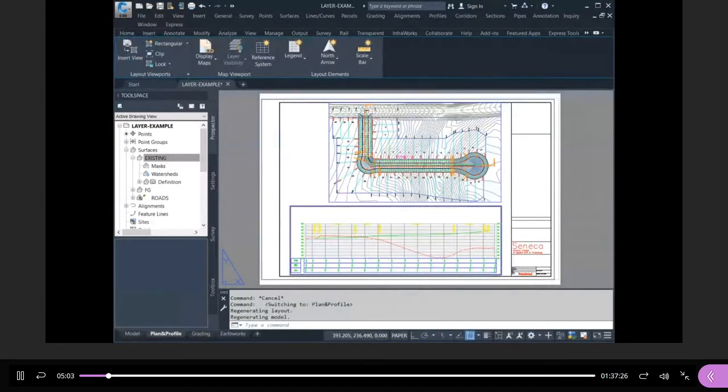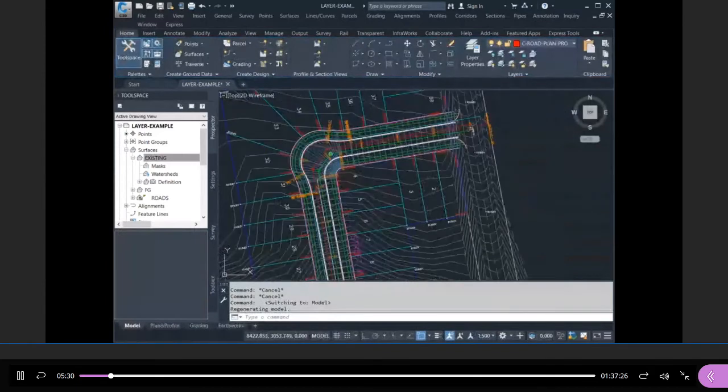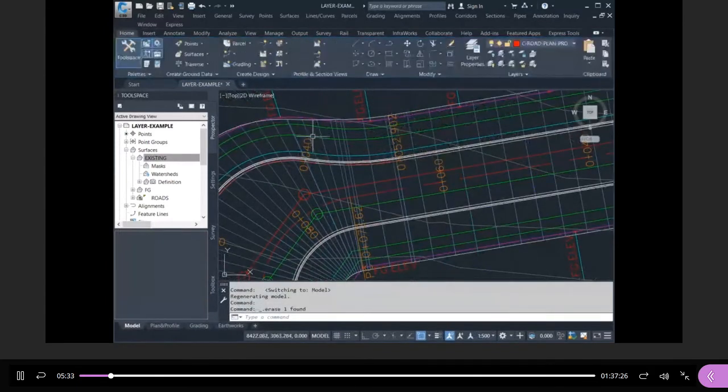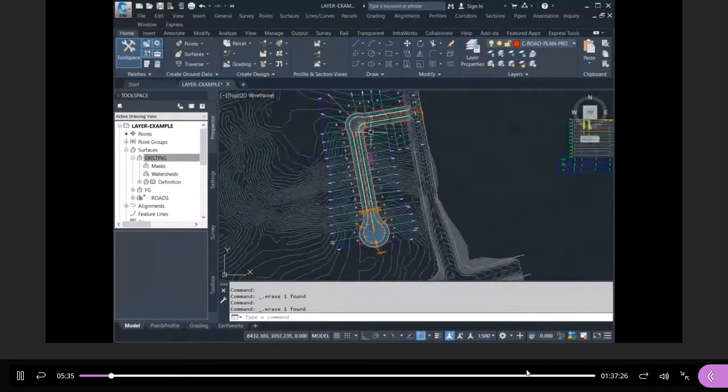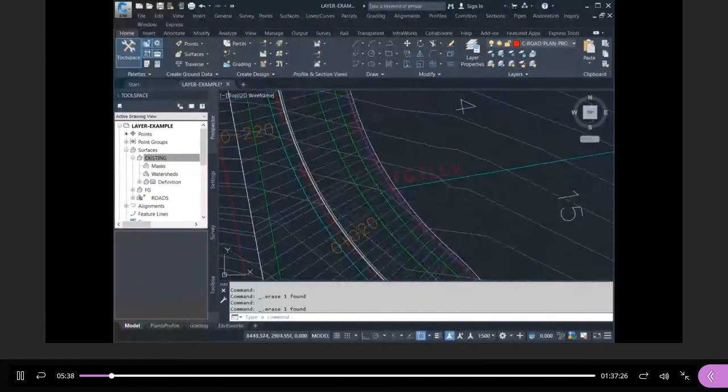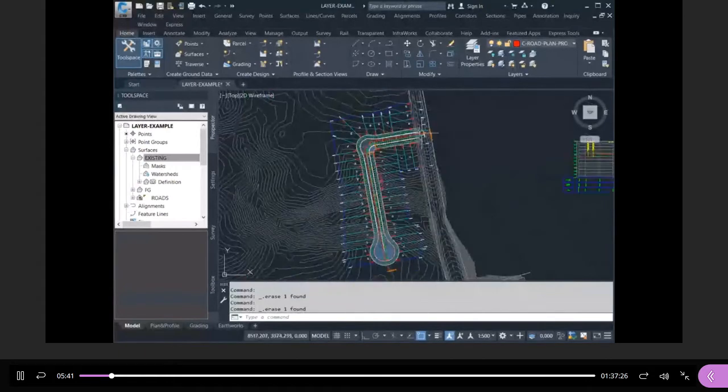The other thing you don't want to see is anything you create to do your work. So for instance, nobody needs to see your corridor. Nobody needs to see the alignment for the gutters. Okay, that's all information you create for the purpose of the surface model of the road. It's not part of your presentation. Nobody sees that. It's implied in the design. It's not shown explicitly. So those are some other things you might need to take care of. Okay, so when it comes to that, this is how I do it. It's up to you. I don't need to see the labels for the crescent. I don't need to see the labels for the alignment of the cul-de-sac, right? The only centerline labels you need is the main road.